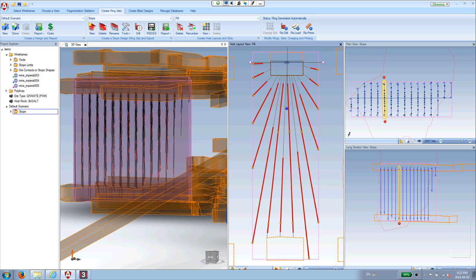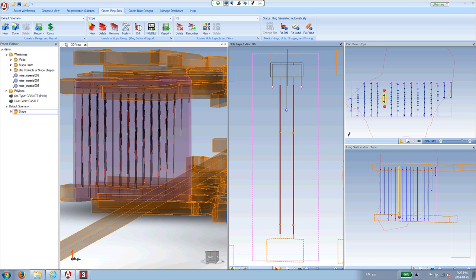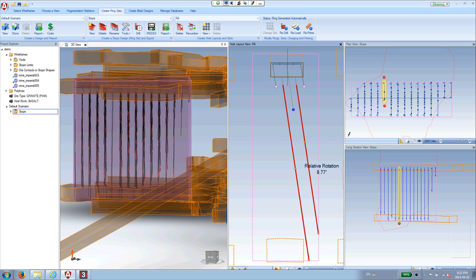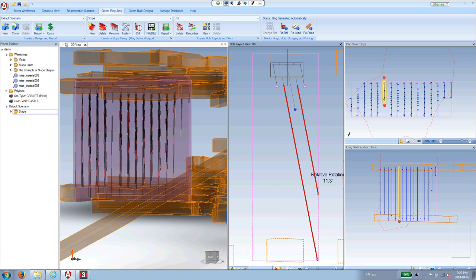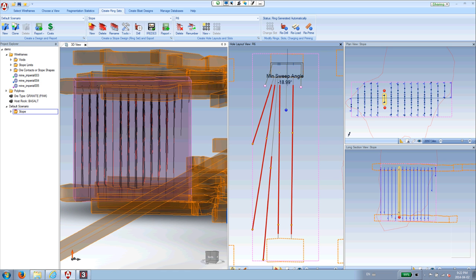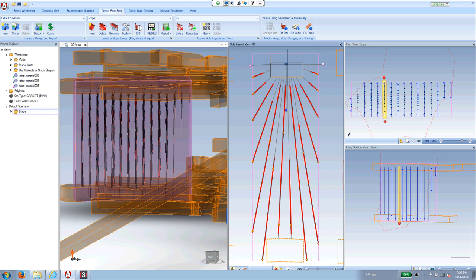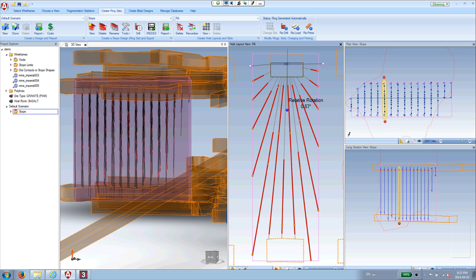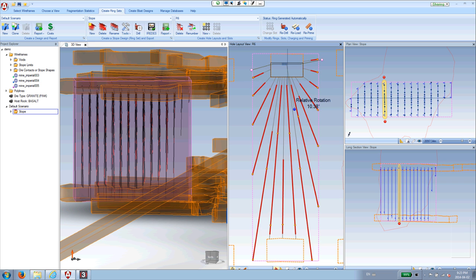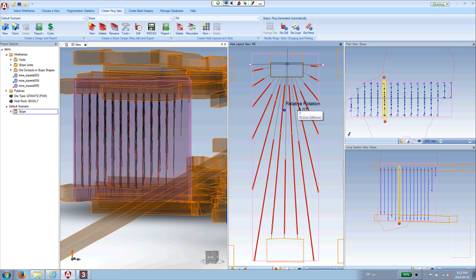With the ring view, we can grab these grip points up here, and I can adjust the sweep angle of the holes. So I can move them all the way down, and then I can adjust the drill direction. I can move that around, and you see how the parallel holes follow the pattern. So if I move the sweep angles back to give us our full ring again, then you can see how the drill direction affects our ring pattern. And notice as I'm moving the ring, the charges are changing, the holes are changing, the priming positions are changing as well.